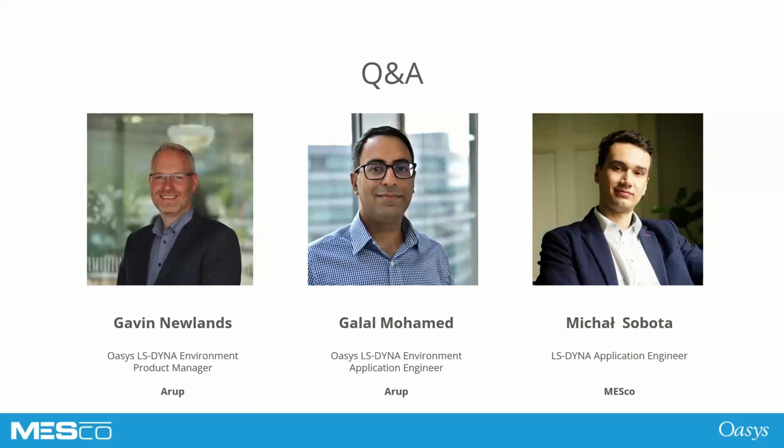When we are talking about the number of elements, I would say that the biggest one was 5 million elements. Using Primer, it was very smooth. I can always hide the elements that I don't need to see. I also showed you D3PLOT, where I can import 2 different models and see the results between them. If I load in 2 models that use 5 million elements, then I have 10 million elements, and so on. I can go over those millions of elements and still have a smooth experience.